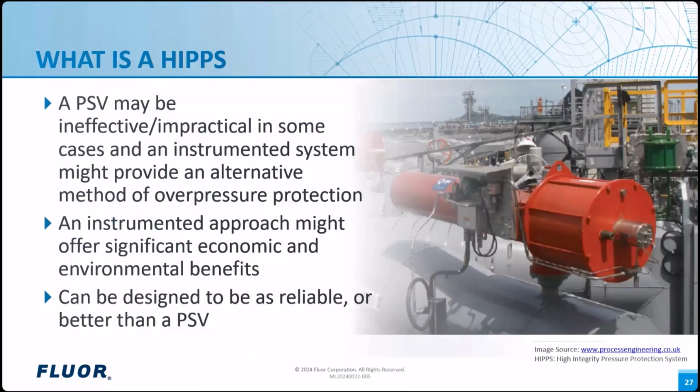For example, due to a very large liquid load to the flare, which would require an impractically large effluent handling system, or for certain services. We have seen examples where the traditional design would have been impractical, for example, to prevent overpressure due to overfill of a propane storage vessel fed by several high-pressure pipelines.